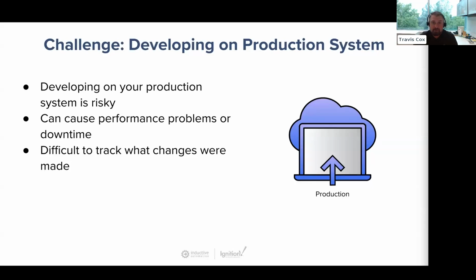For a lot of organizations, they have one Ignition server at the plant that's connecting to all the plant floor devices, bringing that data in, historizing that data, providing alarms, and providing visualization or applications to various people around the company. And as Ignition being unlimited, they can go into the Designer and they can add new tags, they can add new connections, they can add new projects very easily and get those deployed quickly.